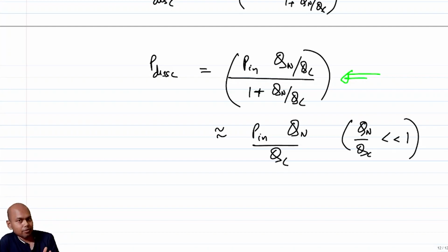So when you are making a matching network with components which have a finite Qc, you will have to design your network in such a way that the overall network Q is much lesser than the individual component Qs. Now that might be weird to think about, because whatever networks we have done till now using only one L and one C, the component Q seems to be similar to that of the network Q, which makes sense because there is only one L and C and one lossy element. But you will see in the next lecture that I'll talk about a framework where you can dissociate the component Q and the network Q to some extent, right?